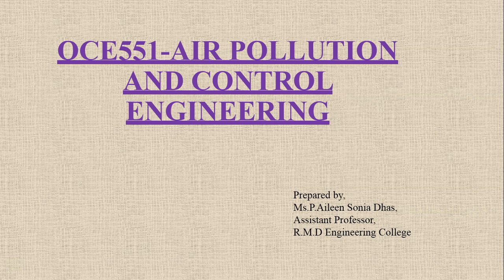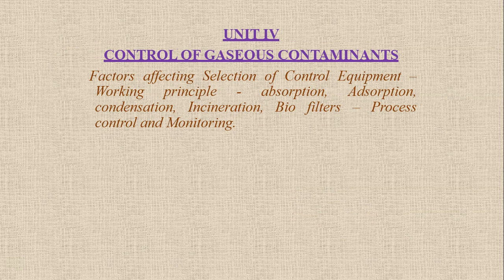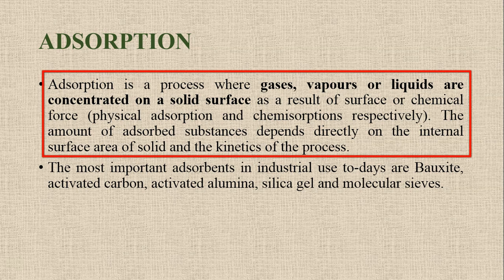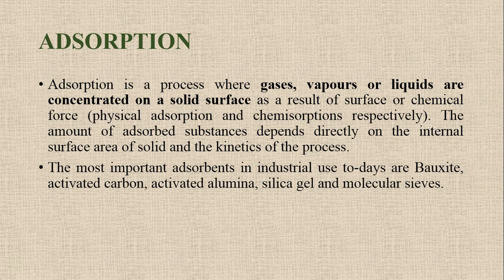So last class, we had seen from the subject Air Pollution and Control Engineering, about the absorption principle. So in this video, we will see about the adsorption principle. Adsorption is a process where gases, vapors or liquids are concentrated on a solid surface as a result of surface or chemical force. The amount of adsorbed substances depends directly on the internal surface area of the solid and the kinetics of the process. So in the last video itself, I had compared absorption with adsorption.